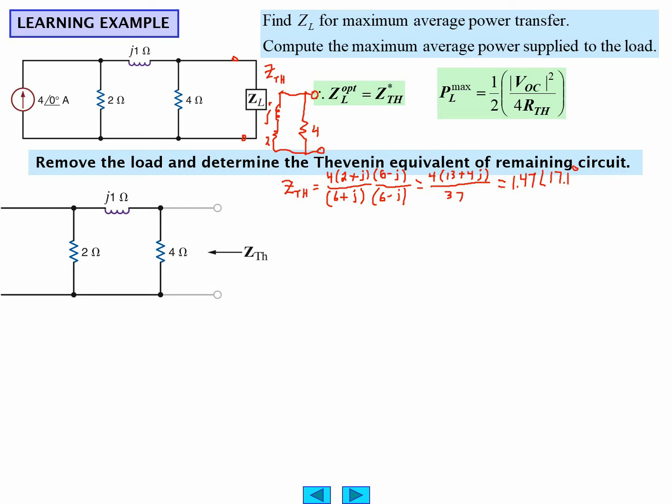Okay, I'm back. We'll keep going with this problem, this learning example. So we want the Thevenin's equivalent between these two nodes right here, here and here. We consider this to be an open circuit. Current equals 0. Infinite resistance, open circuit. So we can redraw the output impedance like this, right here, and write down the expressions.